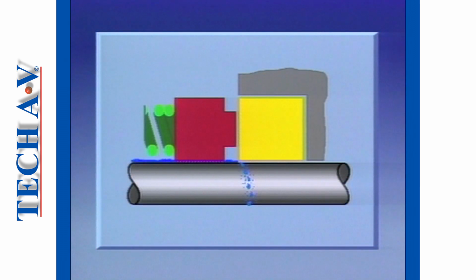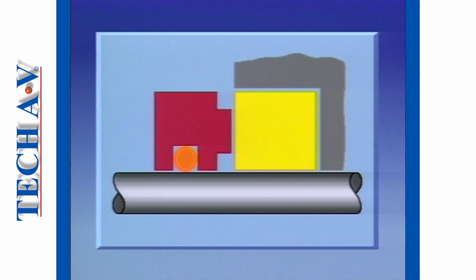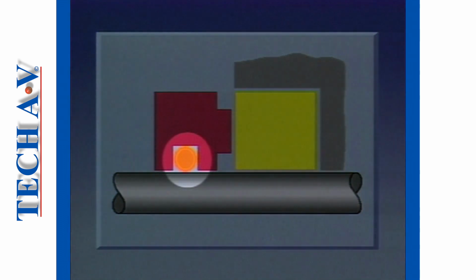Now, having created a basic seal, we still have areas known as leak paths that require extra sealing. Such an area is created between the shaft and the primary seal bore. To prevent leakage in this area, we need to create what is called a secondary seal.